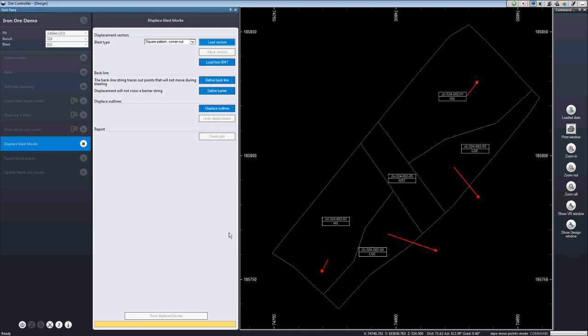I'm assuming in this that you understand the BMM system. It's a system in which you place BMMs, blast movement monitors, into additional holes within the blast and locate their positions before and after the blast using an instrument that picks up radio frequency IDs and will give you the 3-dimensional vectors of movement in different places within the blast. And that's the rather unlikely looking set of displacement vectors that were measured for this particular blast.